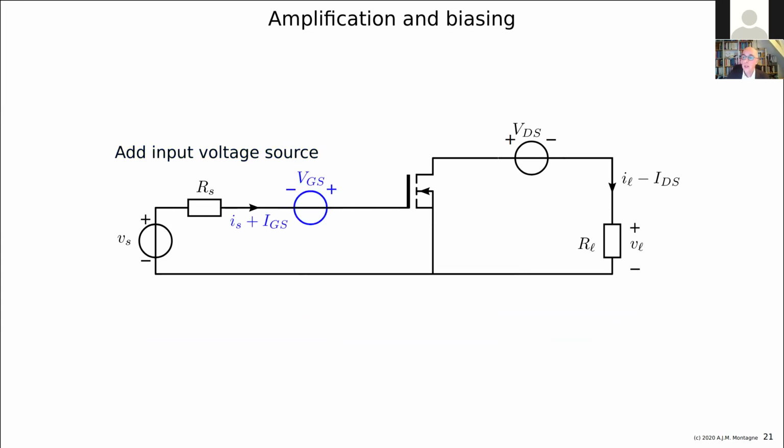Something so that there is always current. Under all signal conditions, there will now be current. We just add this threshold, maybe a little bit more, and then there will be currents flowing, IDS through the device, drain source, and IGS at the input. And of course, for FETs, this DC operating current IGS is usually assumed to be zero. It's a little bit of leakage current of a few picoamps maybe, but for bipolar transistors, it can still be there.